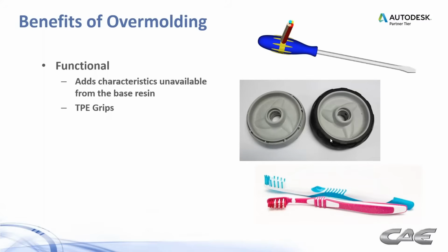That's insert overmolding and 2-shot overmolding in the same thing there. So the metal piece of the screwdriver is the insert. We mold one type of plastic over that, and then another type, the grip for it over that. So there are very functional reasons to use 2-shot overmolding.